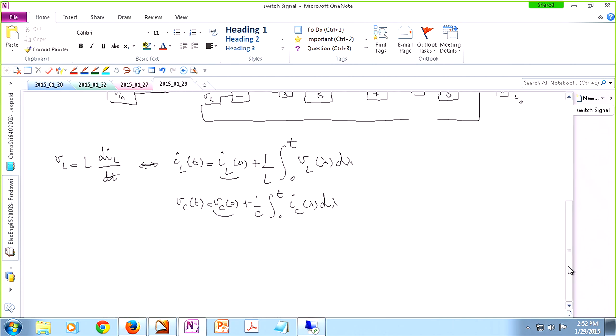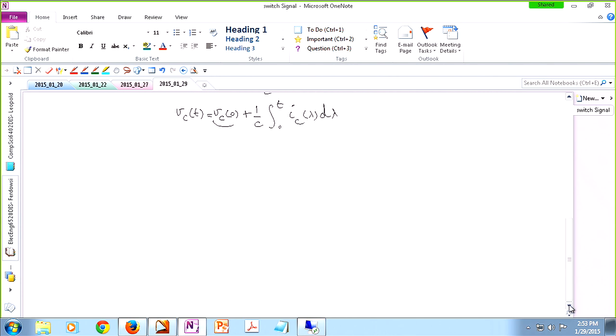For instance, when you're building a buck converter, as it turns out, you need a gate driver that is a floating gate driver. So let me draw. Let's say we have an IGBT. The way an IGBT works is if you apply a positive voltage from gate to source, the device turns on. If you apply 0, it turns off. So technically you need a pulsating source over there, and you have your main source over here.